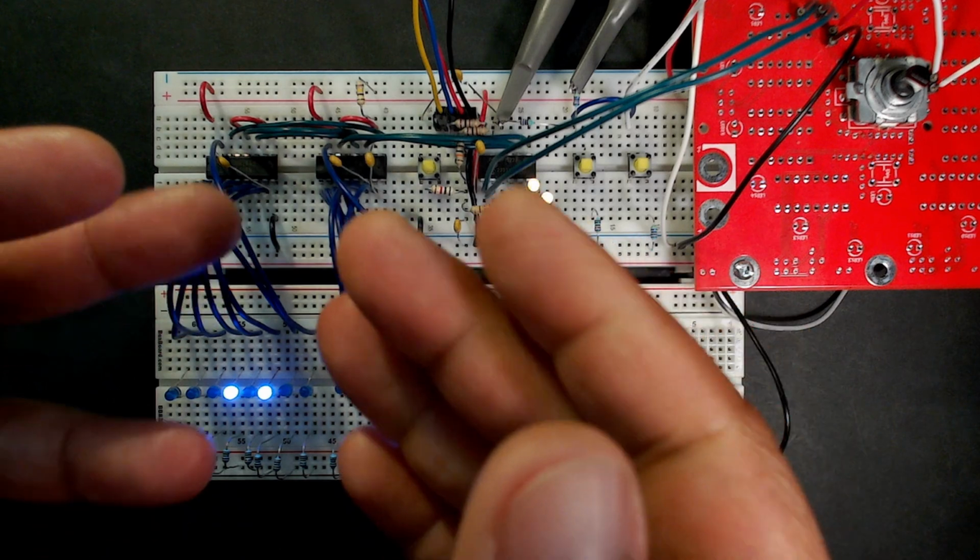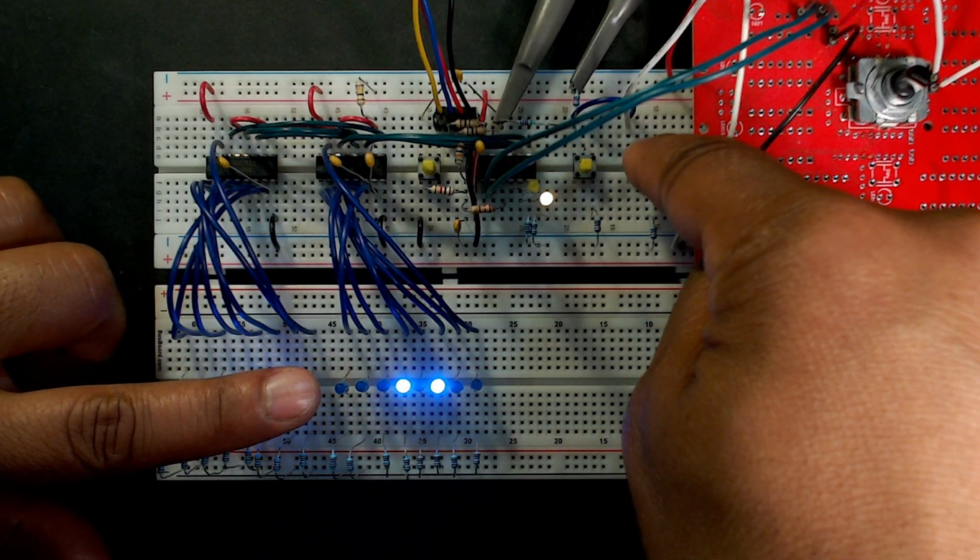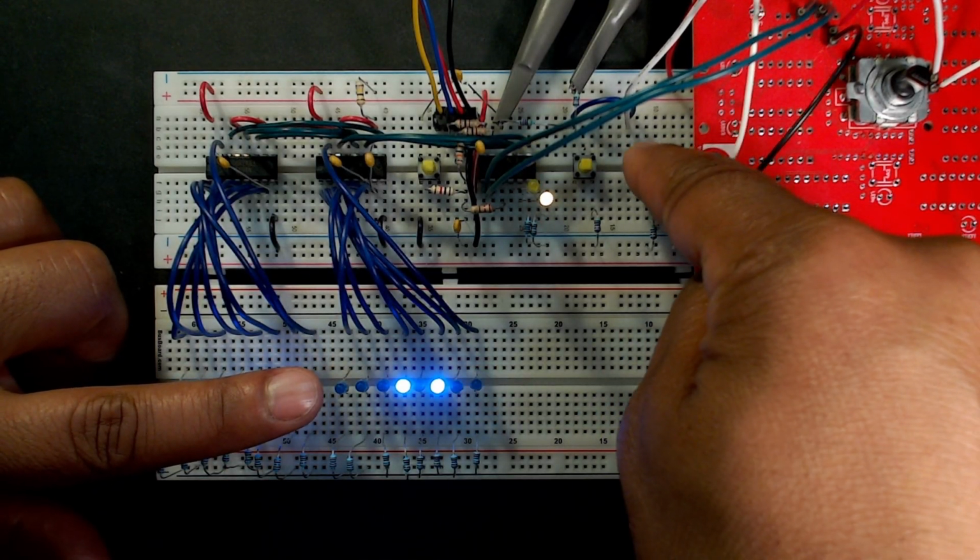Remember, the analog to digital conversion is doing the conversion every single time, and there is some error inherent in that. And there's also error inherent in my circuit. I mean, look at this. This is just a mess of wires on breadboards. So I would have to expect that there are going to be some irregularities there. Hence, sometimes we get one result and a few times we get another result. So in our code, when we interpret those results, we have to acknowledge the fact that we're not always going to get exactly the number that we expect. Now, there's a few different ways we can deal with this, and I'm going to show you two.